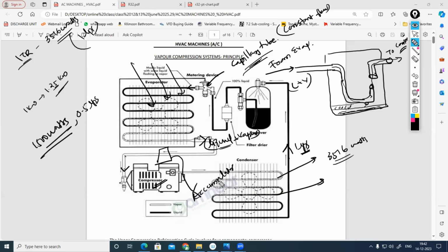Correct. Then now we can see a little amount of refrigerant, due to this scenario, we are storing within the accumulator, right? Still it is liquid only. We are storing it within the accumulator. So the rate of flow of refrigerant through the loop will be decreasing. Mass is decreasing, right? That's why the amount of refrigerant going through the loop will decrease. So the evaporator will be getting enough refrigerant only after some time. Okay. Then what about this liquid refrigerant?